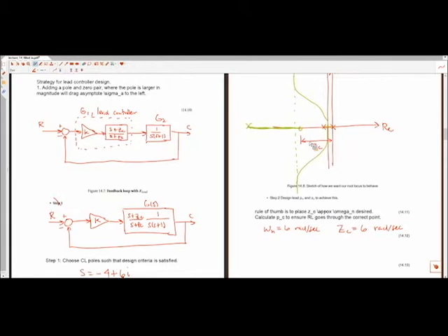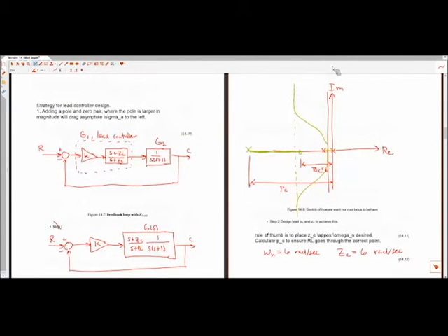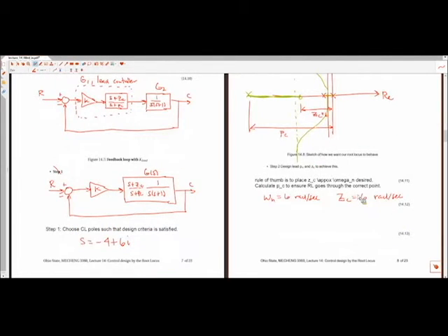Yeah. So then the remaining thing to do now is we're trying to understand what value of PC or pole location will ensure that somewhere on this root locus it intersects this point, which we specified as -4 plus 6i. All right. And so we can actually do this. If we have a ZC selected, we can make sure with 100% certainty it goes to that point. And so this is coming directly from the angle criteria that we've learned in previous classes.